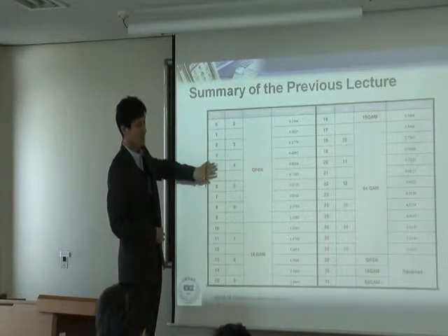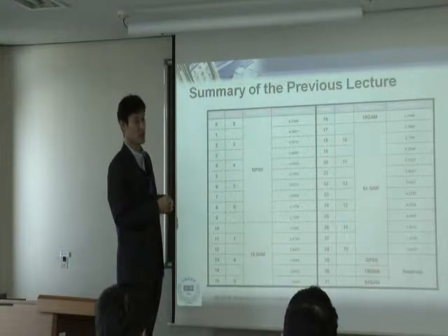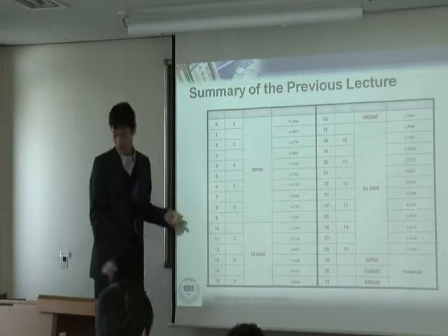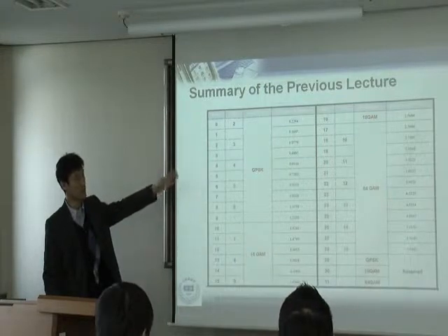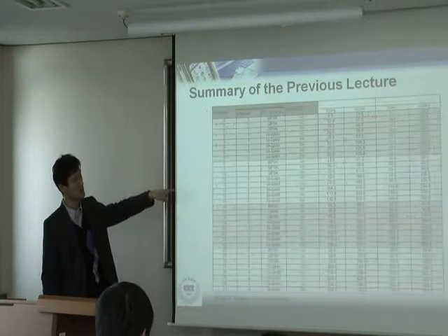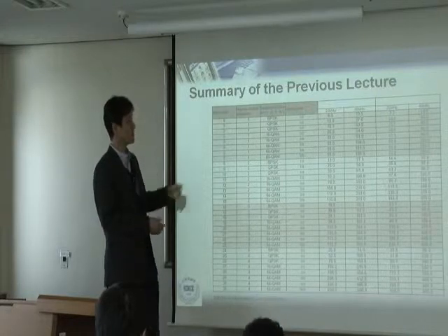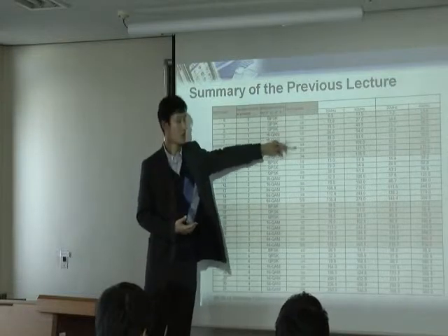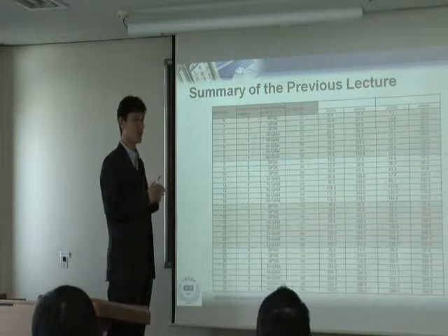When you look at this table, and every system these days has this kind of table, an MCS table. For example, you probably heard about WiMAX, LTE, and 802.11n. This is wireless LAN. LTE and WiMAX are cellular systems, mobile cellular systems. As you see here, these days every system uses adaptive modulation and coding. They change the modulation, and they also change the coding rate. But each system has a little bit different approach.